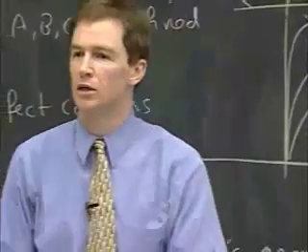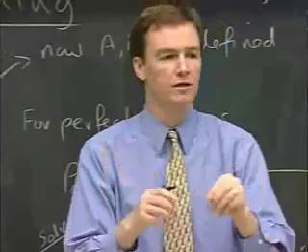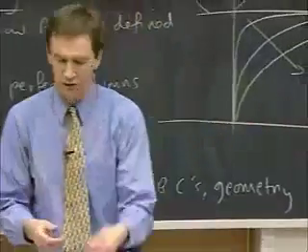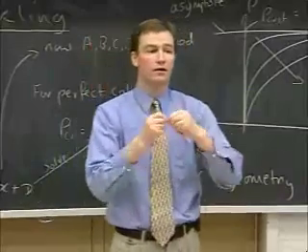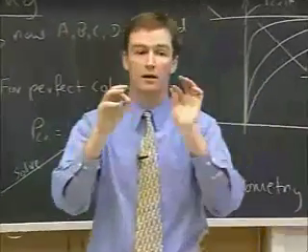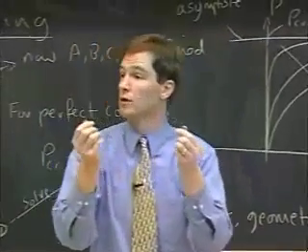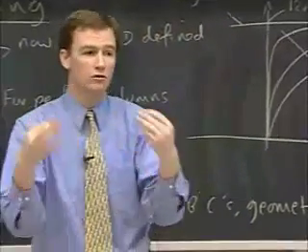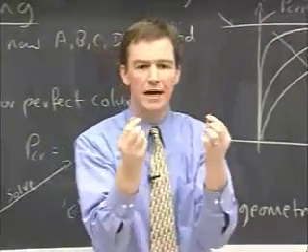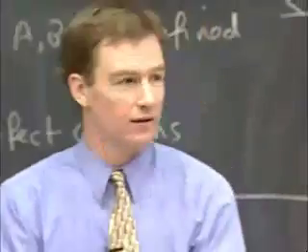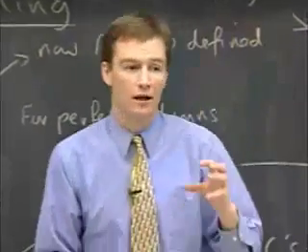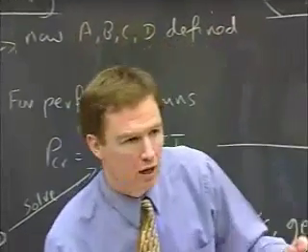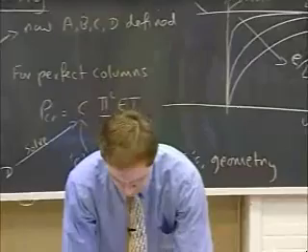You bend a piece of metal beyond its elastic limit, it's permanently deformed, it's failed, at least for this purpose. Then I get mad at it, and I do some cyclic loading on it, and after a few cycles of bending it backwards and forwards, it breaks into two, and that's a fatigue failure, a failure under a repeated cyclic load. So the same bit of metal that was performing quite happily, elastically, holding my papers together, was overloaded, plastically deformed, and then with repeated cycling, it failed. That's the essence of what we're going to be looking at, what governs those different failure processes.